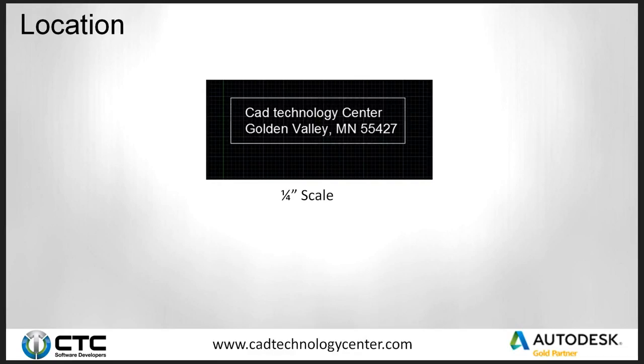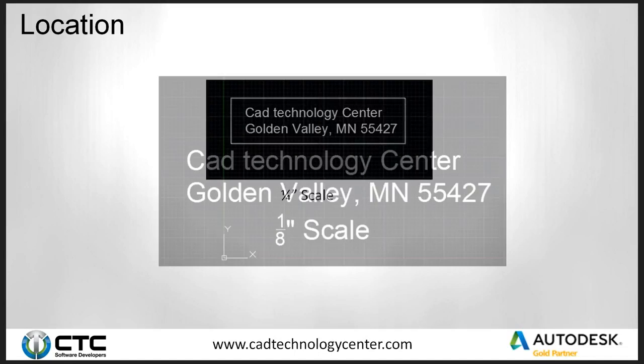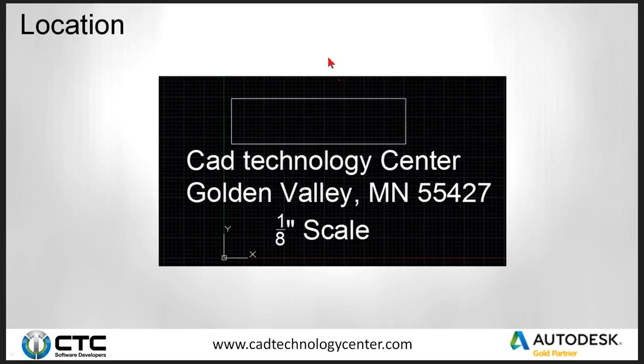But what happens if I have to go to 1/8 inch scale? Well, that text, as you can see, is much larger than the box. So I can't keep the text inside that box because it just won't fit. I have the ability to move it, because moving it outside the building footprint makes it legible. So when I go into paper space to plot, it looks good.